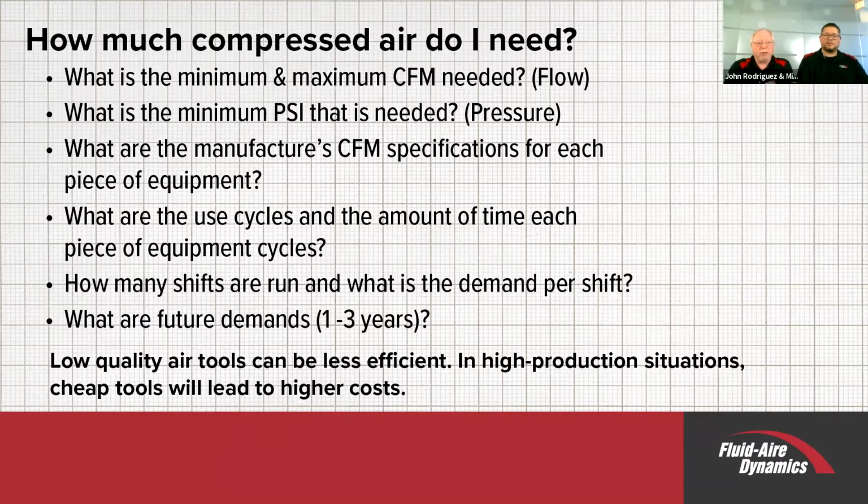As far as sizing the compressor for CFM, all the manufacturers have a CFM specification along with the pressure that you needed at that CFM point. And again, you have to look at not only the CFM that particular piece of equipment will use, but what are the cycle times? How many times is it used a minute or in an hour? Or do they ever hit all at the same time? These are things that you have to look into.